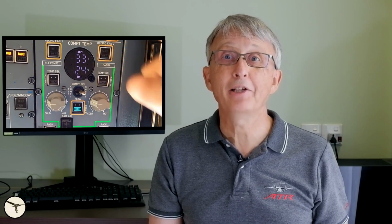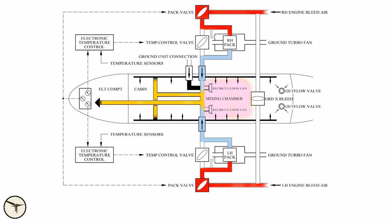3. If the duct temperature is high, select the recirculation fans off. The recirculation fans take hot air from the cabin and mix it with the cold air from the air condition. Therefore, switching them off will improve the cooling of the cabin. Once the duct temperature is cool, you can select the recirculation fans back on, as they provide better airflow in the cabin.